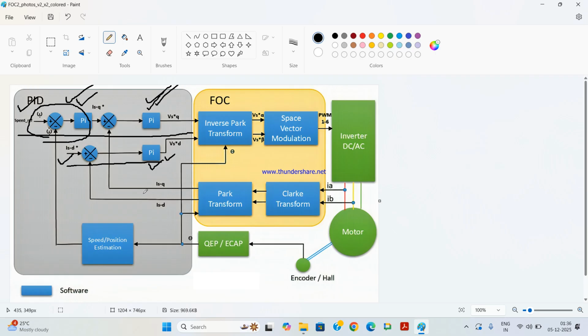So with this, as I was telling, till today I have tuned nearly 40 medium voltage drives all over the country. While we are doing this, the first job I do is the no load run. The passive parameters like motor stator and rotor inductance, resistance, all these things will come from the motor design data, the motor data sheet.